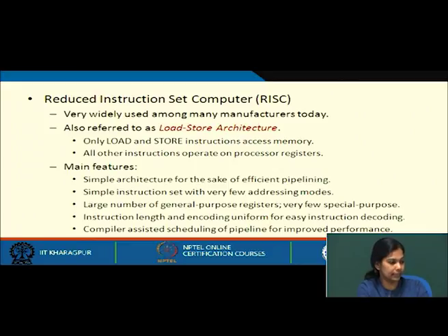Simple instruction sets are used and very few addressing modes are used. It does not support a variety of addressing modes. Limited addressing modes are used in this machine, but it has a large number of general purpose registers, and it does not have many special function registers. Rather, these general purpose registers are used for special functions.